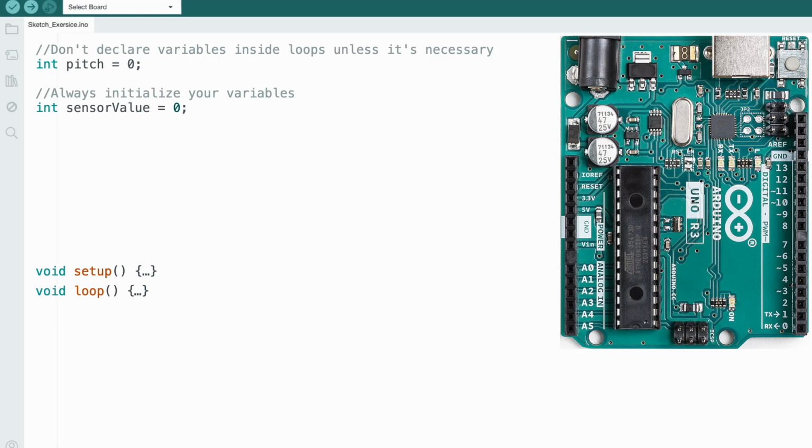Additionally, we are looking at our sensor value, right? The value that we're ultimately going to set for our input. And here, they don't initialize it in the book. I'm a big fan: you always initialize variables. I don't know why they didn't initialize it. A lot of times, you'll get the advantage of a VM, like JVMs for Java. They'll initialize your variables, but when you're dealing with embedded systems, smaller boards, you're not guaranteed that, so always make certain that you initialize your variables. So anyways, enough about that.